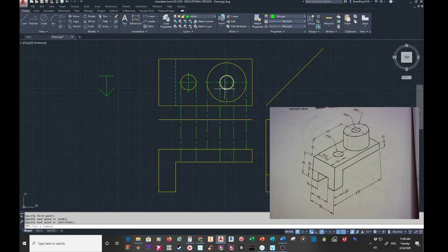That would tell you that it went so far down and stopped. But we don't have that on here, okay? We don't have that symbol, therefore we assume, even though you're not supposed to assume, that this hole goes all the way through.